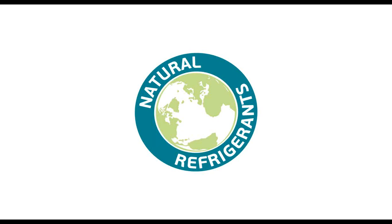Okay, not technical, but I thought it was relevant. Does R290 have the rotten egg smell of typical propane? No, actually, R290 will be completely odorless. The smell that you get from, say, grill-type propane is an additive, and those additives would actually damage the compressor. And this is part of the reason why you can't use the propane that you buy at Home Depot in the system. A, because of the moisture content being too high, and B, these additives would damage the compressor itself.